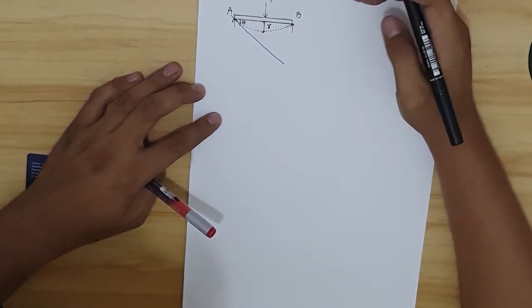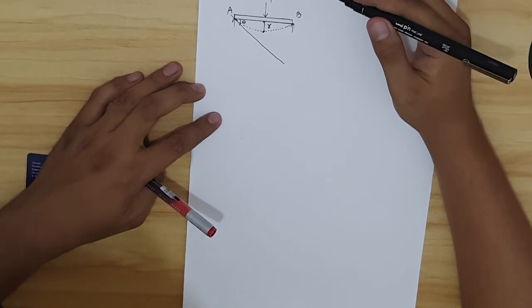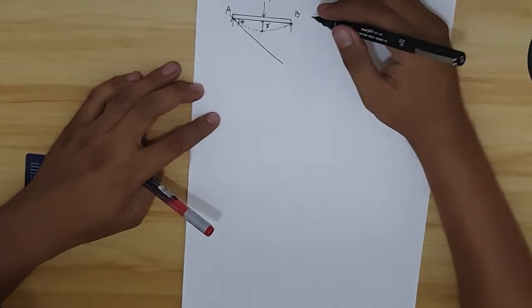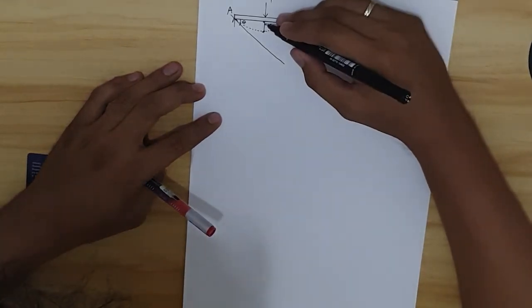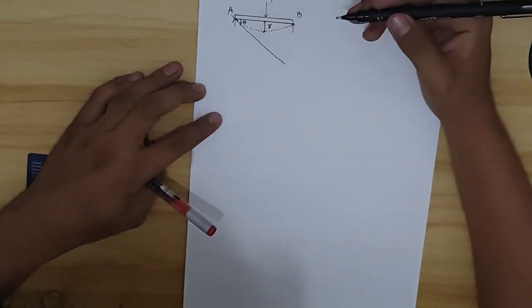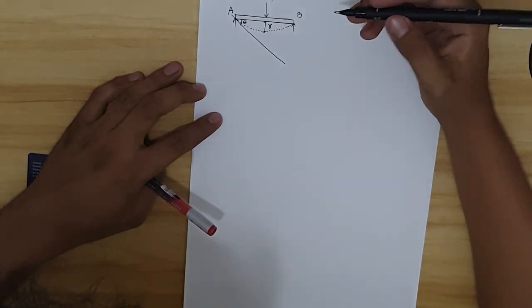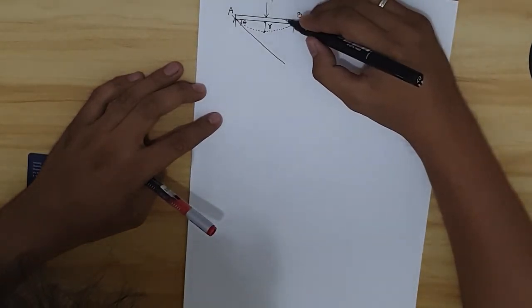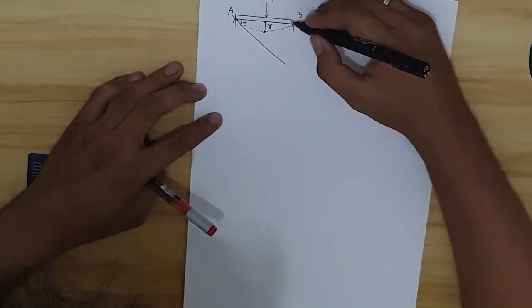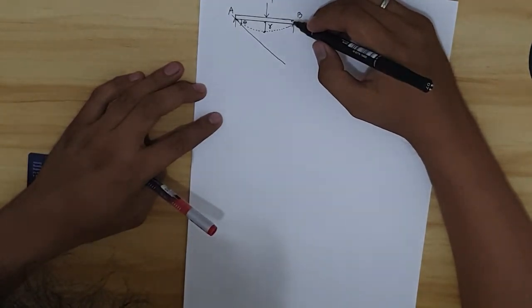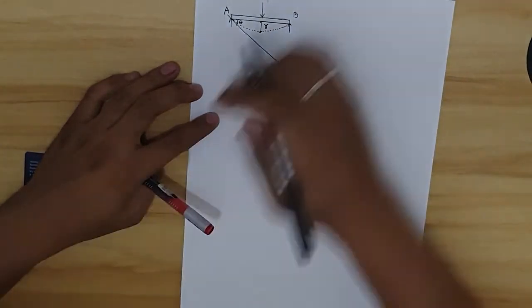But for us, mostly deflection refers to the distance displaced. Okay, so that is the deflection. In checking the structure, we have a minimum requirement for deflection. Say for example, for a beam, mostly L over 360.